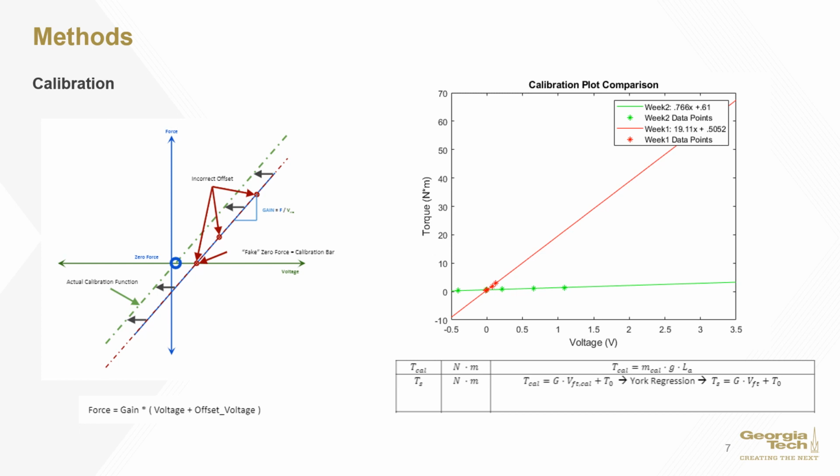To calibrate the torque sensor, measurements from the torque sensor in union with the force transducer are needed to create a calibration equation. From this data, torque calibration gain and torque calibration offset are found and used with given variables to complete the final calibration of the sensor.